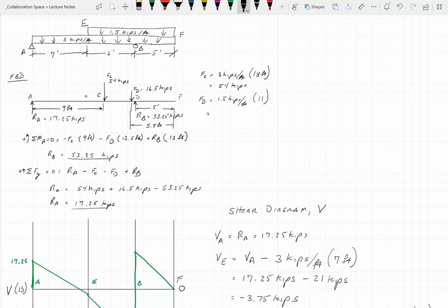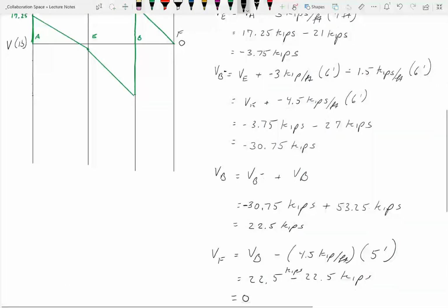So knowing where all those points are is where you're going to put your line. So if you haphazardly draw a line at C down on the shear diagram, it will look okay, but the numbers aren't going to work right because your distances are going to be too far off. All right, so let's see how much fun we can have with the moment diagrams.